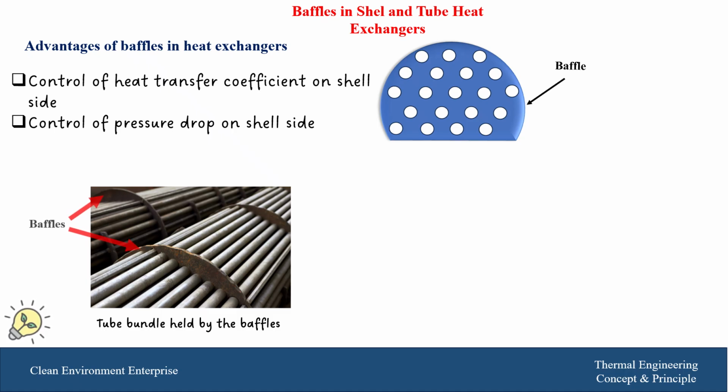So usually these two parameters should arrive at a compromise, because the pressure drop is counted for the power required to run the pumps, and this heat exchanger is only part of a big layout and the network of these piping systems, valves, and other equipment. So we should minimize the pressure losses inside the heat exchanger.